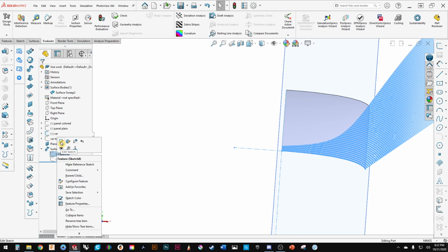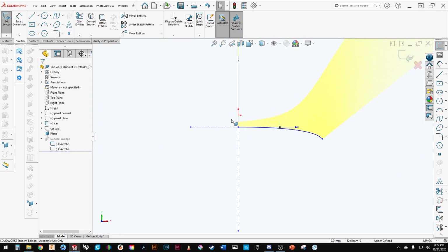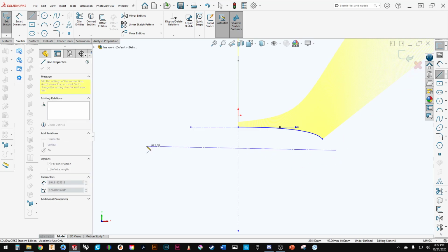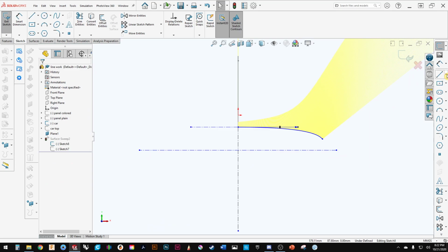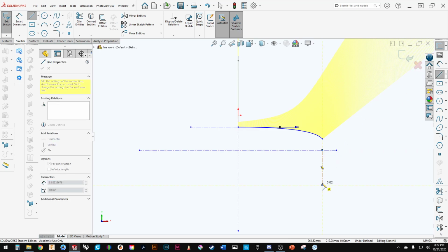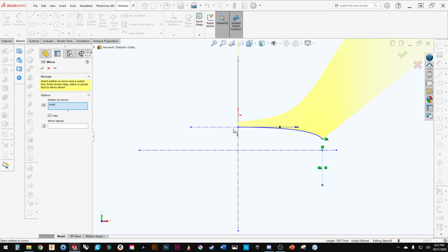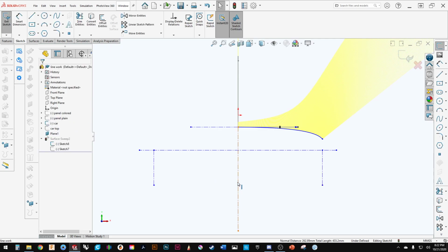And the problem that a lot of people experience is, well, if I'm going to do this, then I have to build the spline all the way across. So let's just say I'll do this. I'm going to build the spline, and I'm even going to do a few more things. I'm going to make sure that the 2 points are the same on each side. So I'll take this construction line, I'll mirror it over here. So that way I know that they're going to both start on both sides. So they're going to be mirrored.